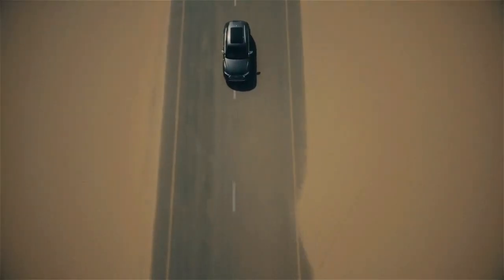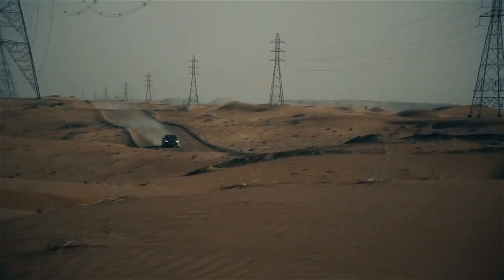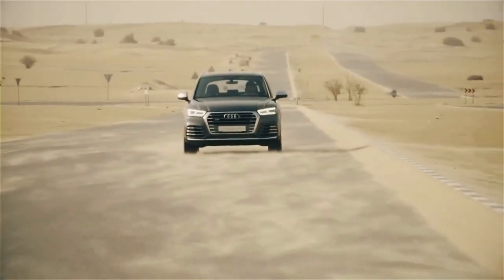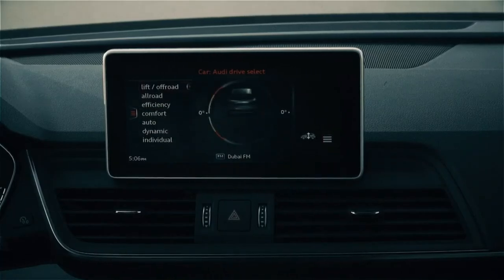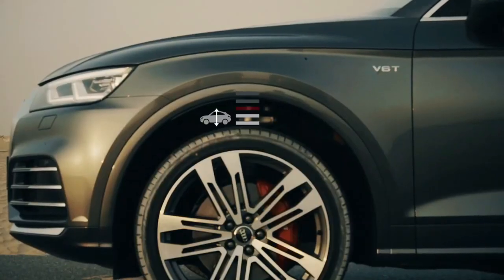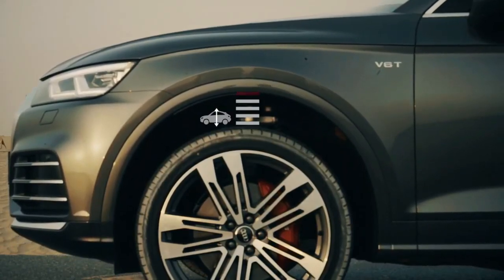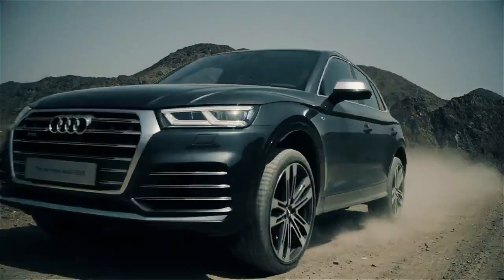Now, after getting the knowledge about the parts used in air suspension system, the question is how the system works. The air accumulator functions as the air supply source for valves that are affixed to the vehicle's frame. These valves are connected to the airbags via supply lines.